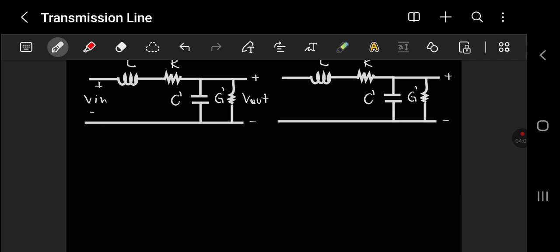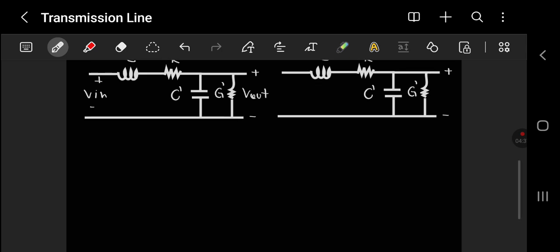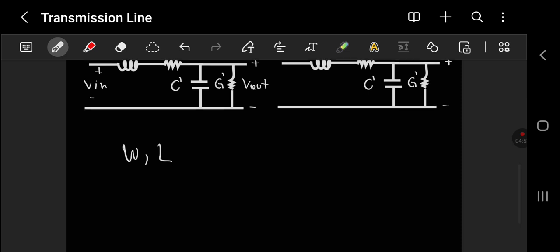Without exceptions, in a piece of coaxial cable or microstrip line, we must consider the inductance, the resistance, the capacitance, and the conductance, since we are modeling these structures based on the electromagnetic fields which spread or are contained all over the dielectric, and we make use of displacement current and conductive current by controlling the width and the length of this structure.